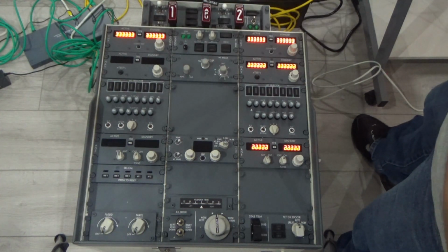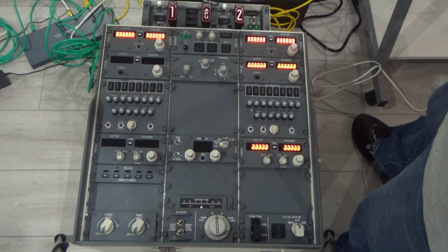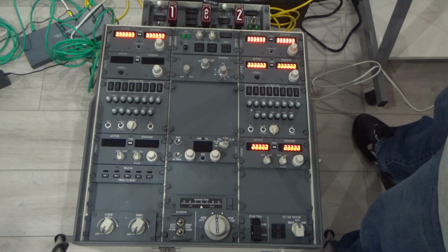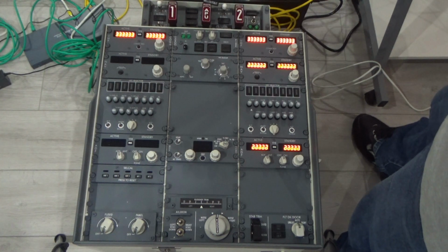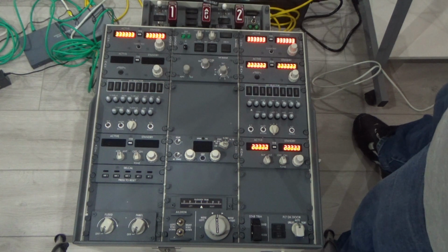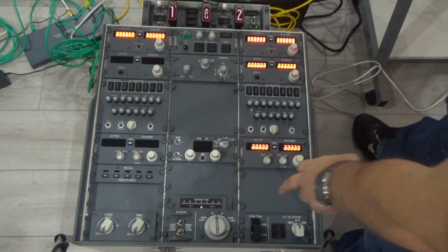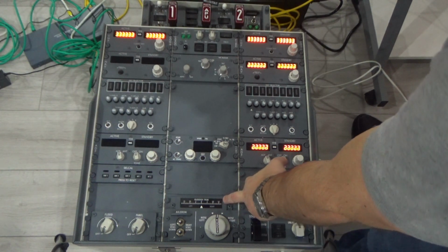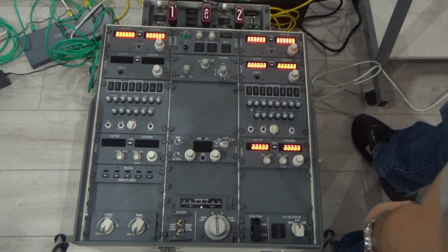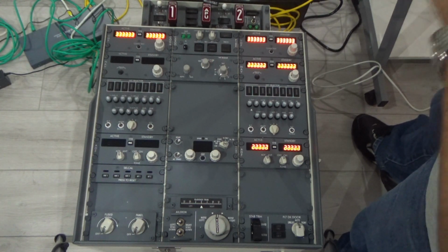Alright, so I've been looking a little bit into the problem. I think there is no problem as such, everything works okay. It's more to do with the servo motor. There is only a certain number of turns they can go one way and a certain number of turns they can go the other way, so it cannot reach over 15 or left 15. I guess I have to calibrate between 0 and plus 10.